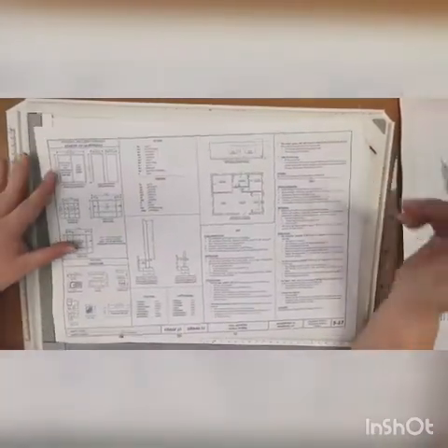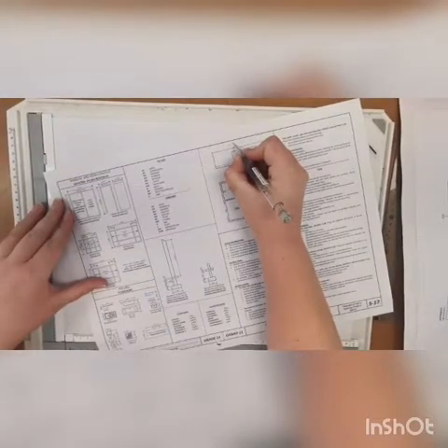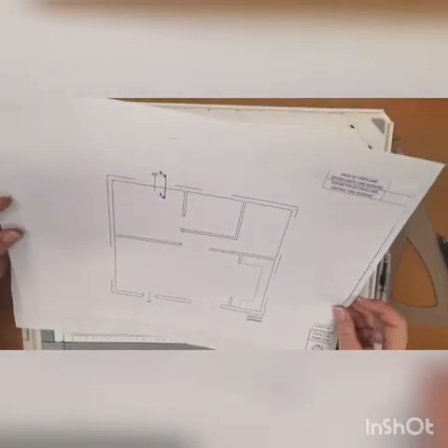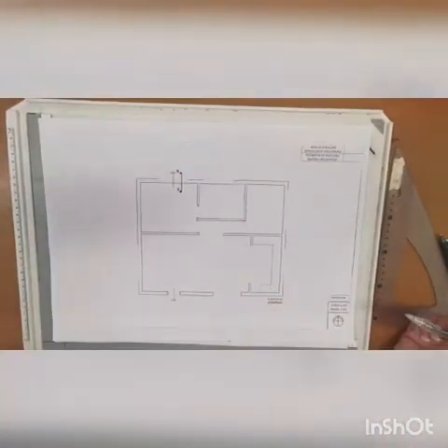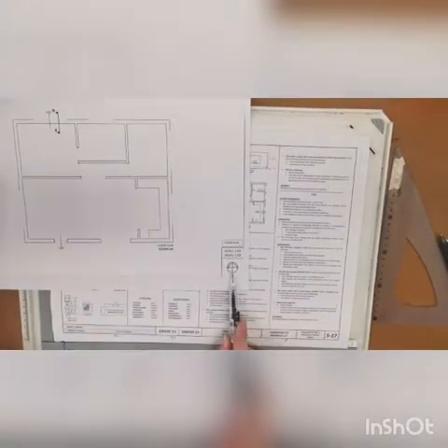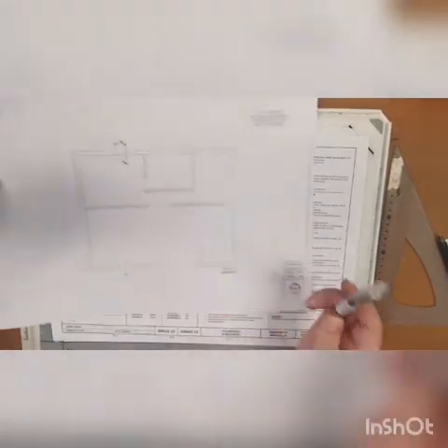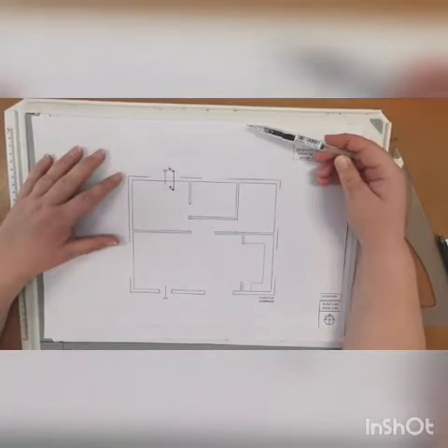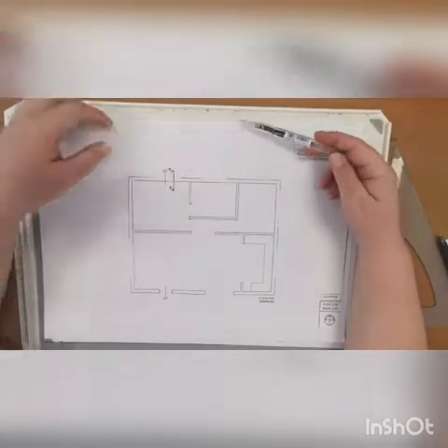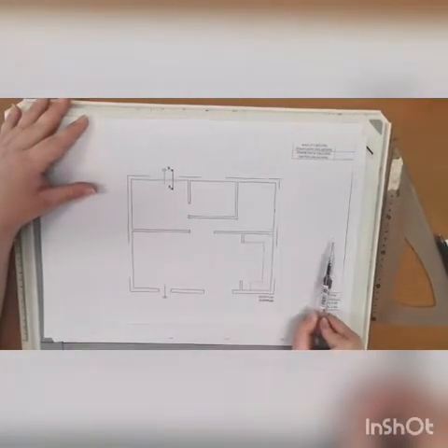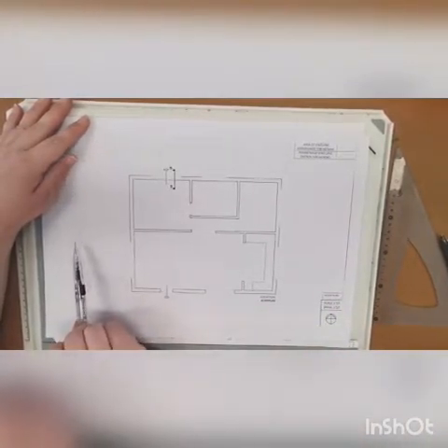This elevation we're going to do at scale 1:50, which is the same scale that was used for the floor plan. I'm going to start by doing a north elevation. Please remember, if I say to you do a north elevation, you look at the north point. The north point points to the north. The elevation is labeled according to the direction they face. This would be a north elevation because it faces north. This would be south because it faces south. This would be east because it faces east. This would be west because it faces west.